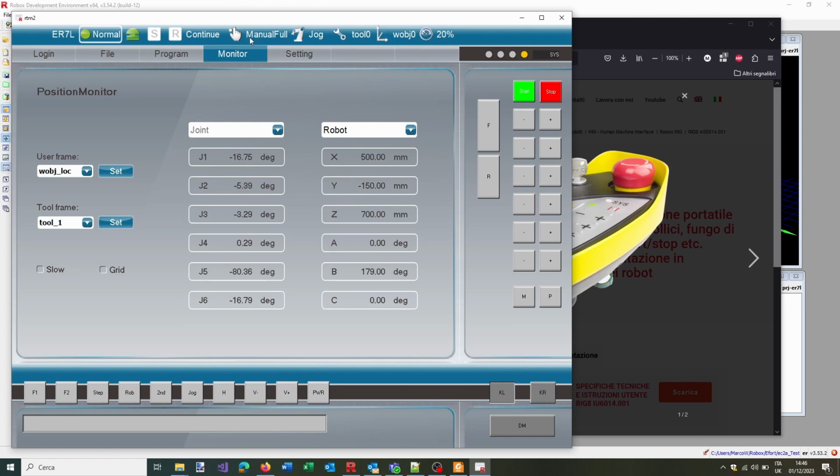They are both manual modes, but normally the manual full is something you would like to select in order to allow the feed rate of your machine to go more than 20%. Otherwise, if you just stay in the normal manual slow, the feed rate will be limited. Now in manual full I can, for example, say 75%, but if I take out the left key, I will go back to manual slow and the feed rate will automatically be limited at 20%.